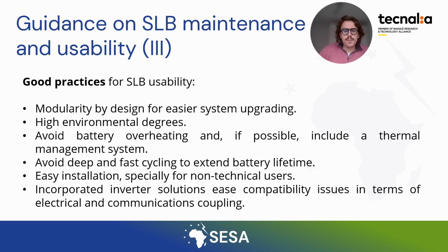For usability, the modularity by design concept is especially interesting in case we want to increase or upgrade the battery system or add a new element to it. Additionally, avoiding overheating situations, but also deep and fast cycling situations, is very interesting in order to extend battery lifetime. For non-technical users, easy installation is a key feature. And lastly, incorporating inverter solutions will help in terms of compatibility with electrical and communications coupling.